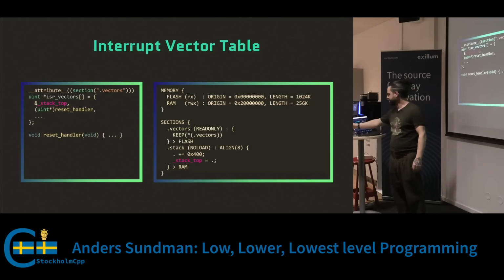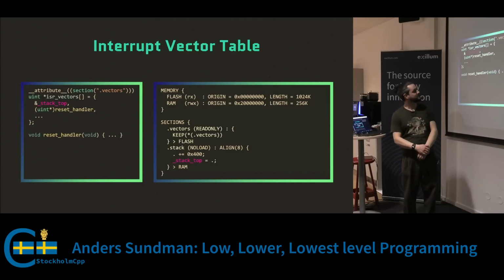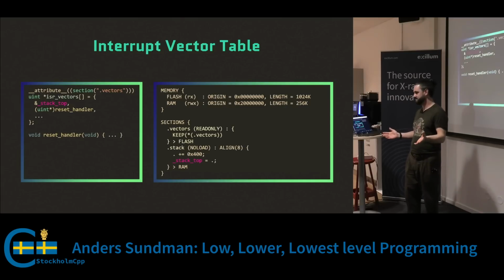I guess maybe it's to be nice to C programmers so they don't have to do it inline. It's very nice. All interrupt handlers also have the same calling conventions. So they need to do it some way, and this is the way it's done for ARM.